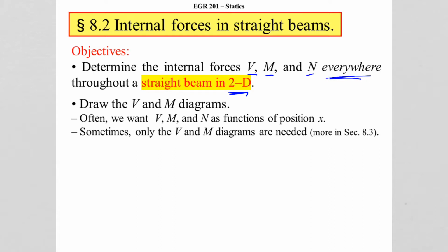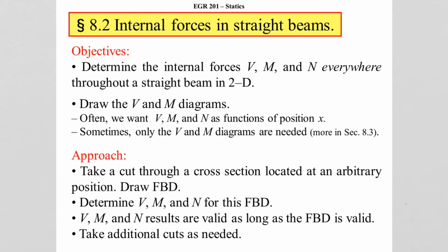straight beam. So we're going to draw essentially shear and moment diagrams so we know what the shear and moment is everywhere within the beam, and we're going to look at it as a function of x. In section 8.3, we're going to deal with it if we only want to know what this is without knowing what these functions are as a position of x. So the method that we do in solving these internal forces is essentially take a cut like we did in section 8.1.